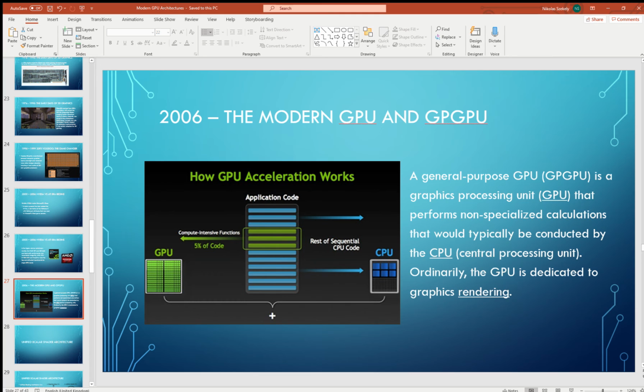Over the years, NVIDIA continued to diversify their feature set in GPUs by introducing the Kepler architecture. NVIDIA realized that more cores running at slower speeds are more efficient for parallel workloads than fewer cores running at twice the frequency. Reducing the shader clock also has the advantage of lowering power consumption, and NVIDIA further economized on the design by drastically reducing the die's available double precision units, as well as reducing the bus width to a more mainstream 256-bit.